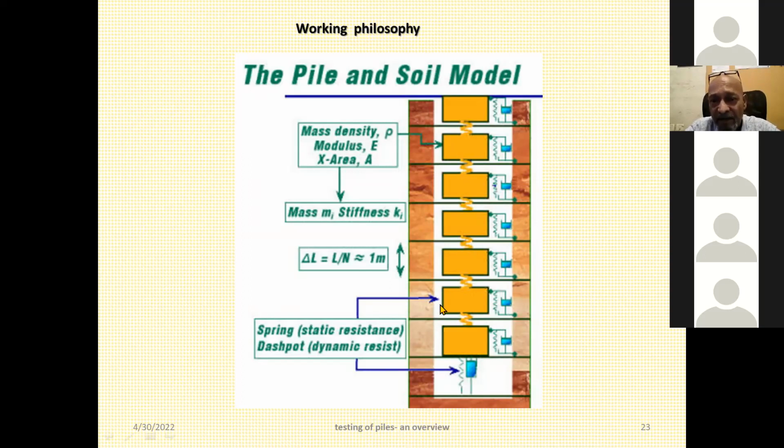The whole pile is considered to be made of finite 1 meter sections of a structural element, and soil is considered as some kind of spring, and these pile and soil interactions are represented in the form of springs and solid masses, so many things go into that.